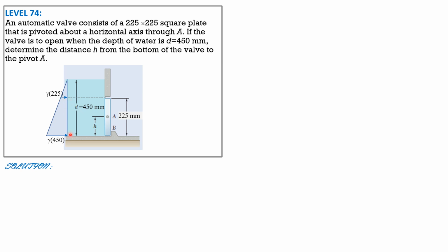And let's divide this trapezoidal pressure diagram. This part is not included because this pressure acts on the wall of another body, so it does not contribute to the force on this square gate.